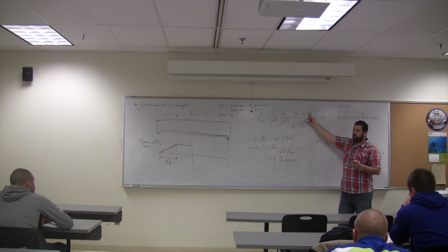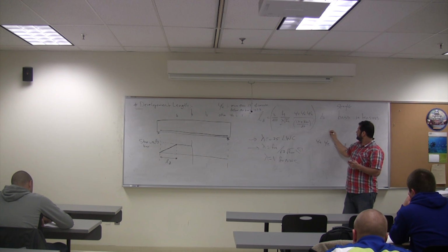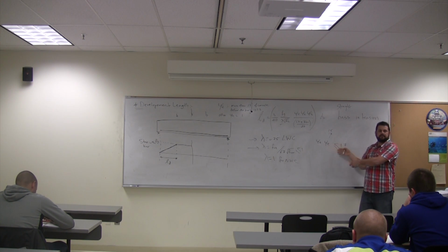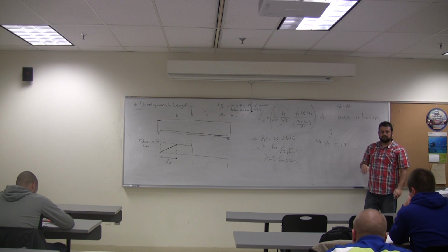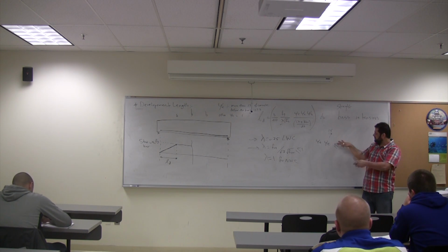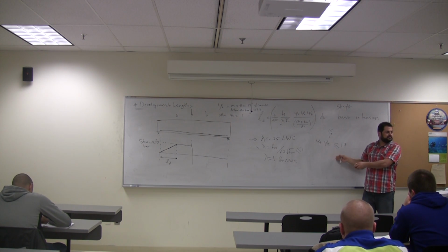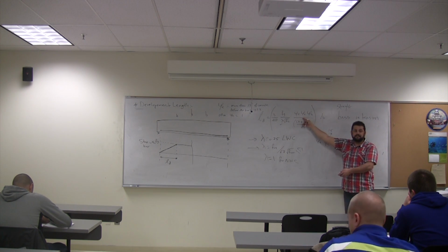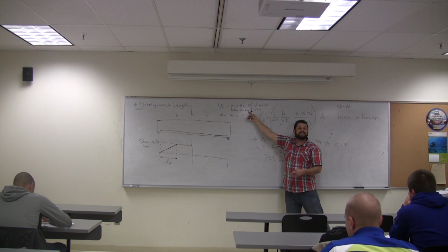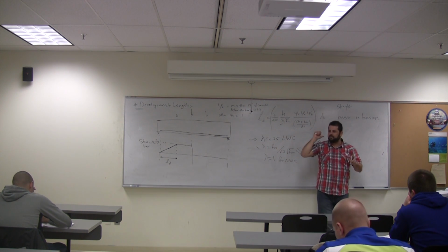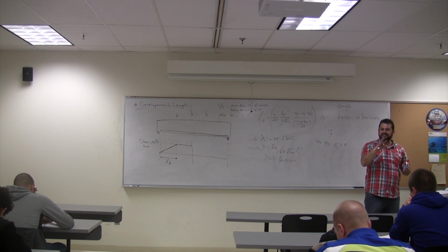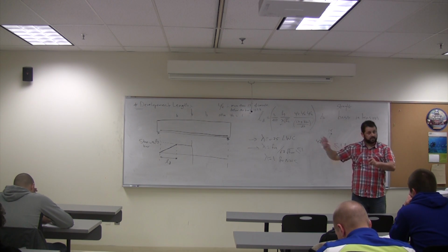This guy here, psi E, can have 1.5 or 1.3 or 1, right? Other than 1.5, this is done. If you have 1.5 for psi E and 1.3 for psi T, the multiplication is more than 1.7, right? So you take 1.7 for both of them. They're saying this is too much exaggeration. Understood?